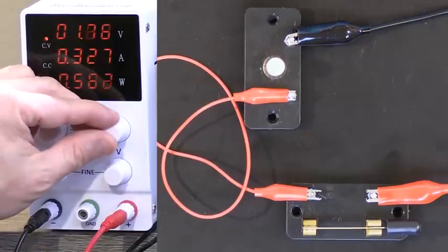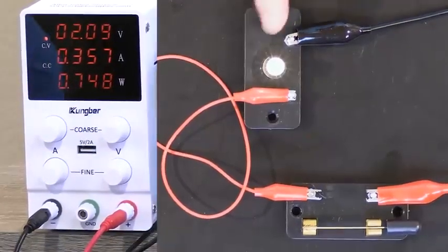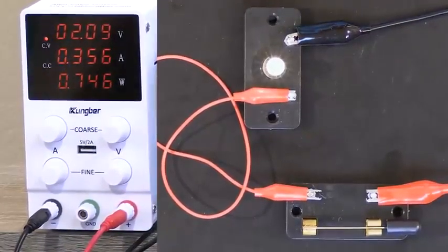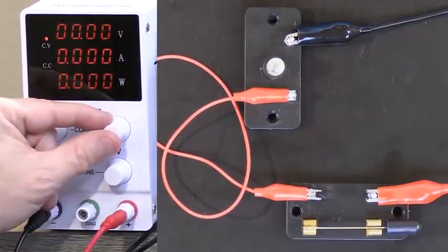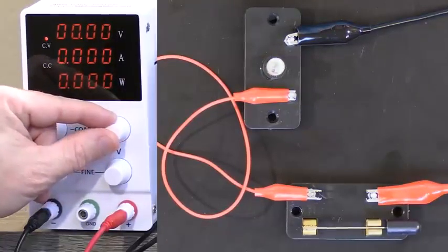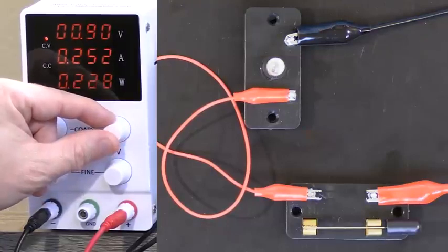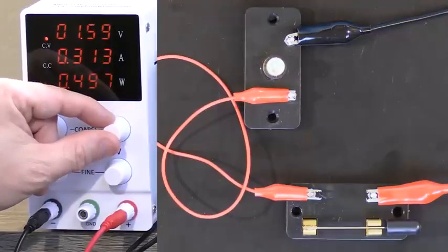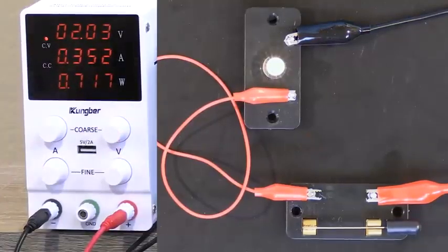Now, if I increase this higher to 2 volts, notice it's awfully bright. If I increase it too much, the light bulb will just get so hot it'll burn out, right? So that can obviously happen. I want to do it one more time and sweep, and I want you to focus on these numbers as I smoothly go to 2 volts. Notice how, as I slowly increase the voltage, the push is increasing, and that's causing the current to increase. And we'll talk about later, but it's also causing the power in watts to increase as well. Voltage is push. It causes current flow.